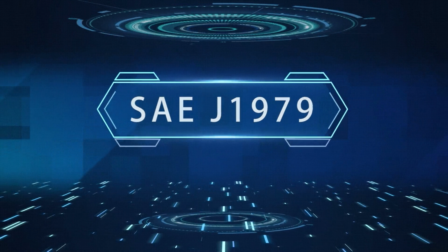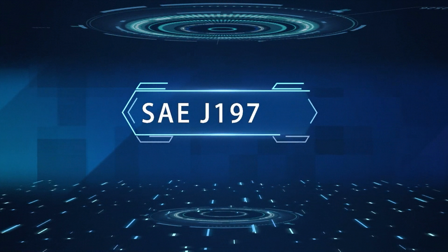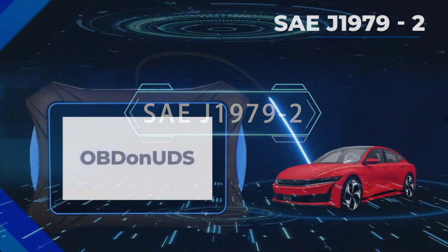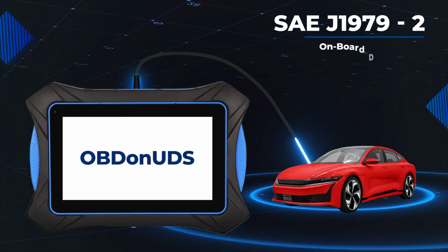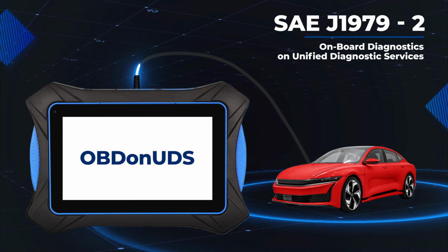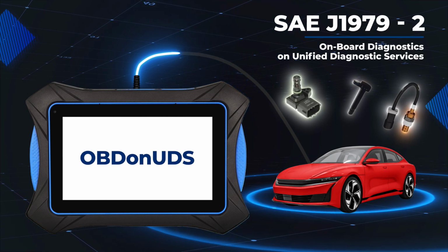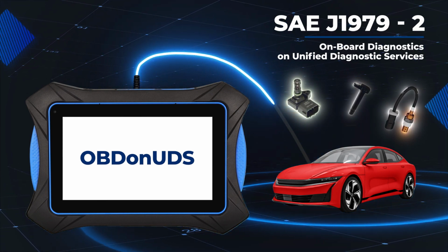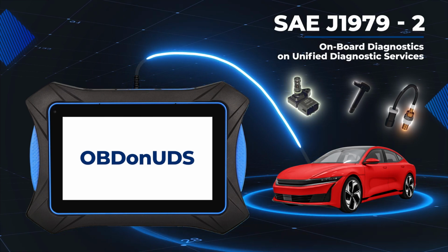The second part, SAE J1979-2, is an extension of the J1979 standard. It defines diagnostic services for OBD on UDS, onboard diagnostics on Unified Diagnostic Services, enabling greater data access, more parameter identifiers, PIDs, and support for advanced sensors.